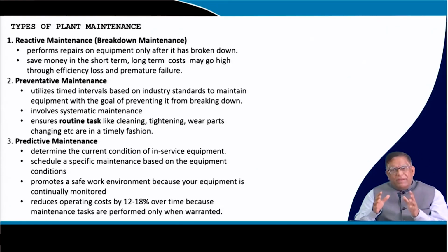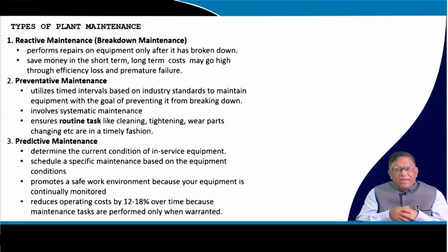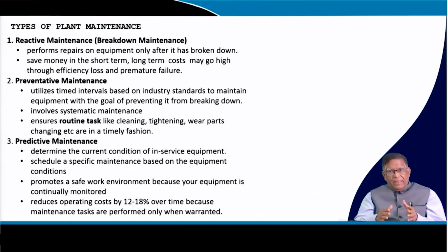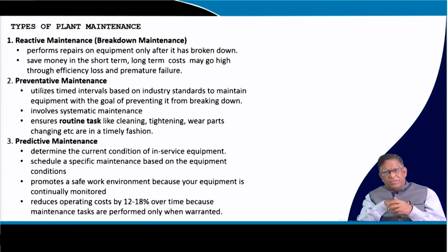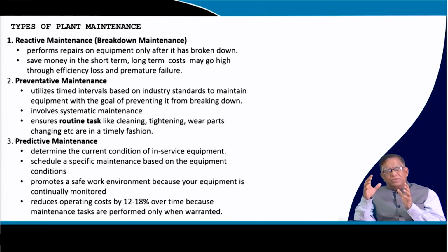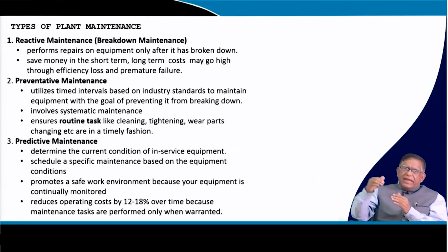By that, the time of maintenance, which earlier was say 2 hours a day that you were stopping, now you can stop only for half an hour, with a little bit of checking, and then your machine will be running. So every day if you gain 1 hour, production time is increased, and if your conveyor belt has a carrying capacity of say 5,000 tons per hour, that means in a month of 30 days about 150,000 tons will be produced additionally.